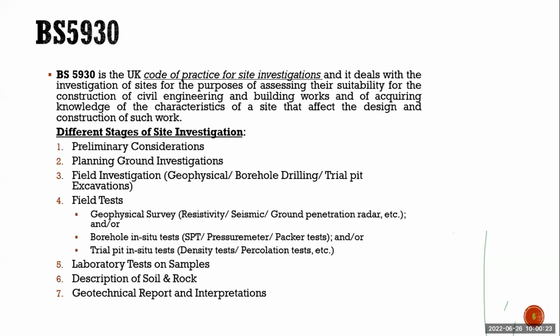You see the aerial map, with the help of Google you can see what other structures are nearby, and you take the soil map and check what kind of soil we are going to get at this project site, and whether any previous investigation was done around this region.